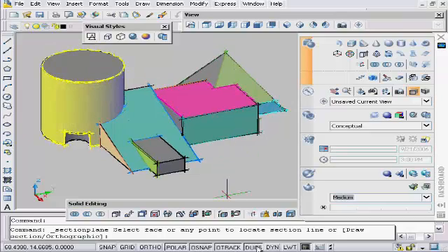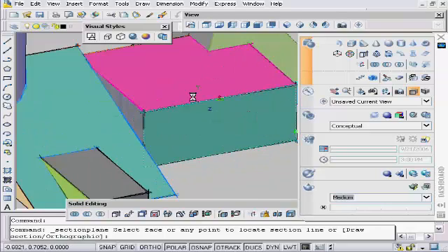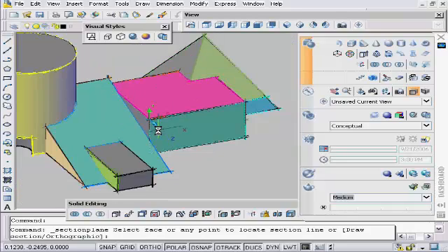Now the first thing we should notice is that our dynamic UCS works with this tool, amongst a lot of the other tools that we have. Watch what happens. When you practice, I'm going to place a section plane. Because the dynamic UCS is turned on, I can use a face to create this. The dynamic UCS is working with our section plane tool, but it works with a lot of other things. When you see that face go dashed, you're using that beautiful dynamic UCS.